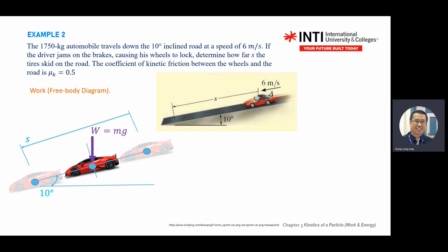There's a contact surface with the 4 tires. I've seen one student who had 4 normal forces on his free body diagram. That is wrong. When you do engineering dynamics questions, try to group all the forces, for example, the forces acting on the tires, under tire force or normal contact. So you have one normal force there.